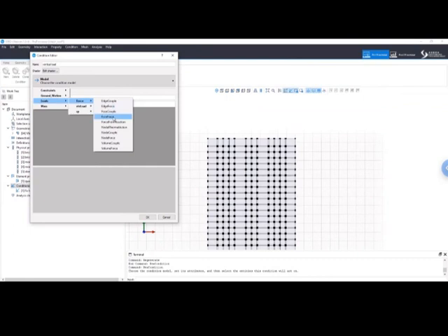And you may ask, okay, but OpenSees doesn't have distributed edge force on surfaces. Yes, but in STKO we did it in the sense that the user inputs a distributed load over an edge, and then STKO does the nodal lumping automatically, so that the Tcl file in OpenSees will have a lot of equivalent nodal loads. So this is quite convenient.